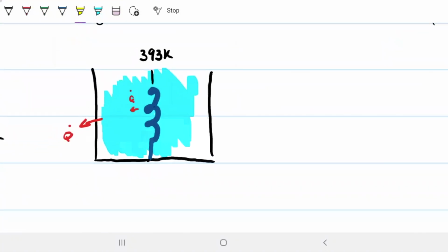So we have this little vessel here. And the way that I thought about this is I drew this little coil. This blue guy here is a coil. And I thought about it exactly the same way as our lab experiment. If you recall, in our lab experiment we had the shell and tube equipment, and a little vessel that was heating up the water so that we could have our hot input. Inside that vessel there was this metallic coil that heated up, and I drew exactly the same thing. I know this coil is passing steam at 393, and this steam is leaving the coil and going into my fluid.